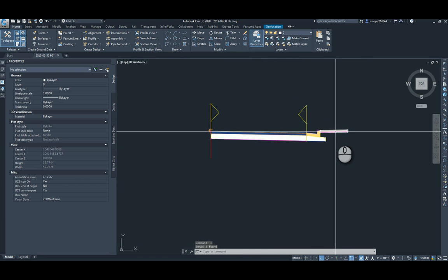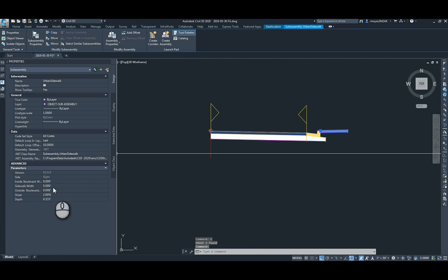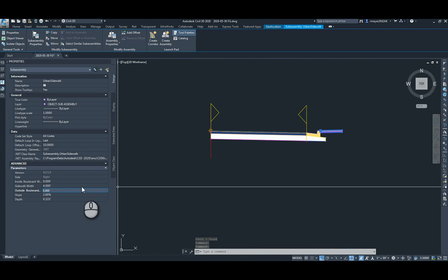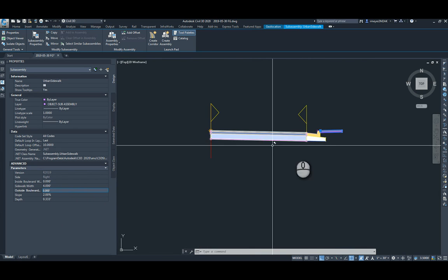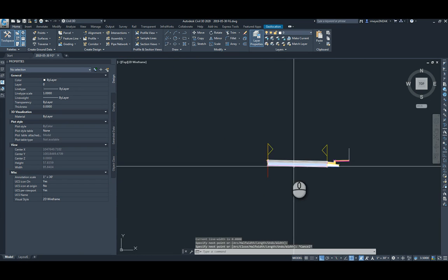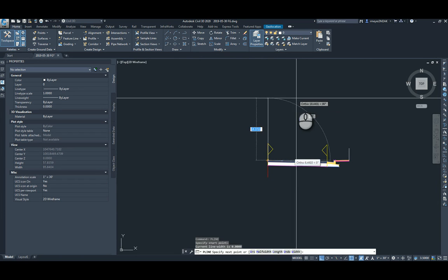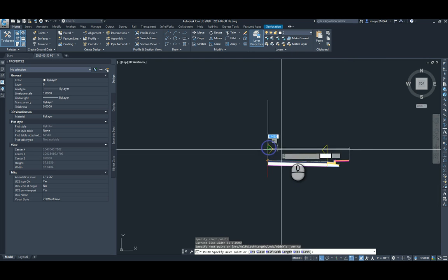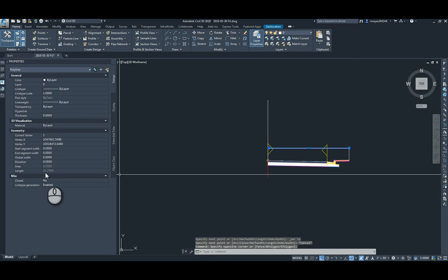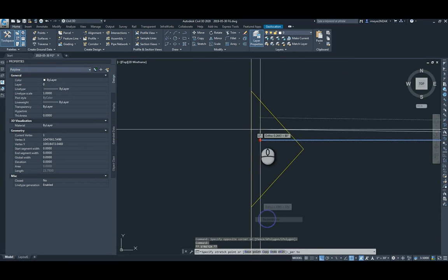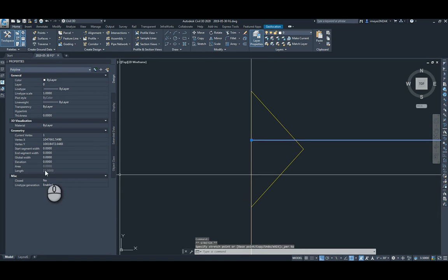And then the sidewalk we also need to change. It's a 4-foot sidewalk, it's not 5 foot for the 50-foot right of way. And then also the outside boulevard, if we take a measurement here from there to here, we're a foot short.